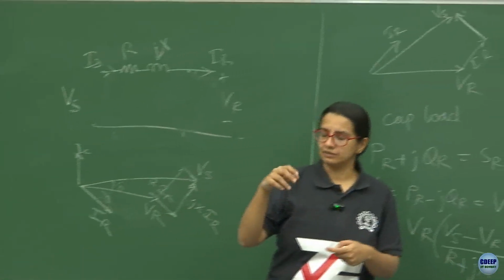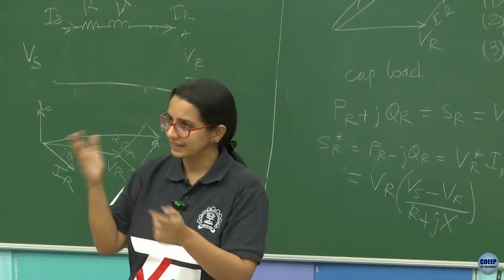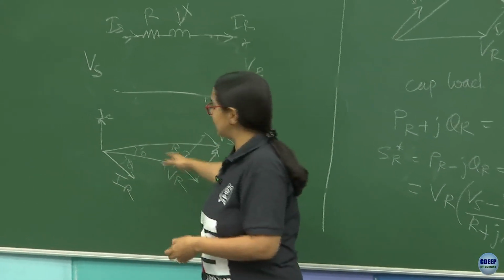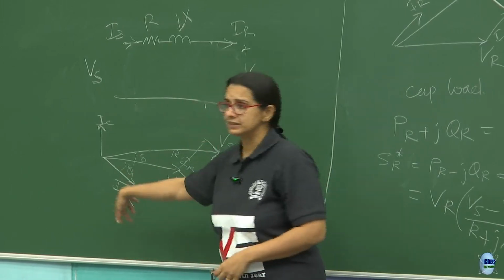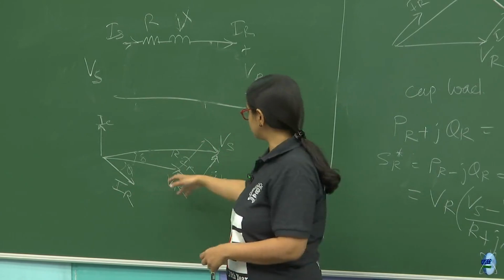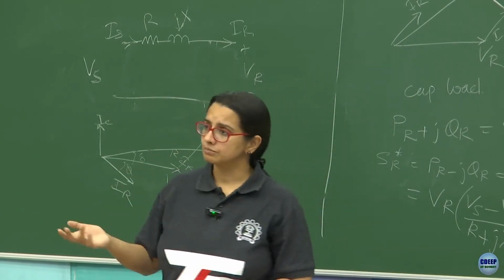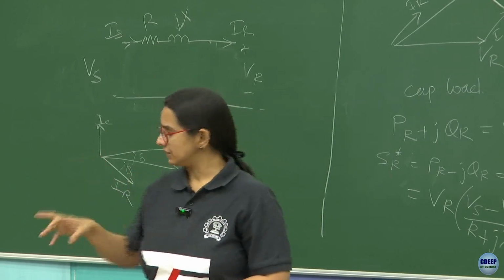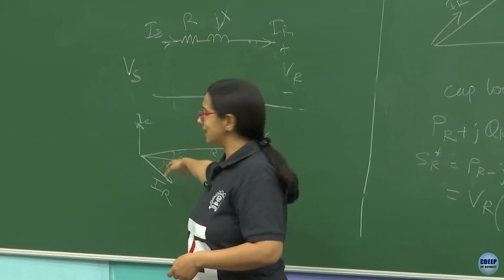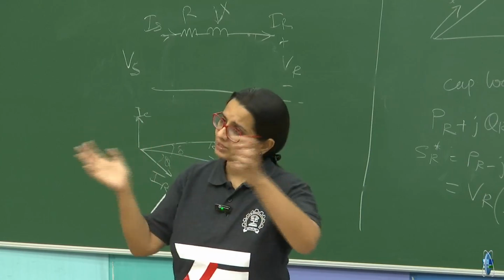So when it affects the capacity, in the sense that you would want to maintain a particular delta, if you were to allow a large enough separation, either because of the current you allow it to draw, or the R and the X you have on the circuit, then that can lead to certain problems in terms of stability. So that is what I was saying. This delta usually, in fact, is only going to be 5, 10, 15 or something. But when you calculate capacity, you assume it to be quite large.